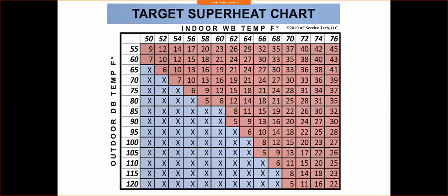It's going to tell you what your recommended superheat is based on the conditions. All right, so you've got this chart, and depending on what your conditions are, you're going to charge the system based on that. One cool app to have instead of having this chart, it's called Emerson's Check-in Charge. Really cool setup. Various amounts of refrigerant out there. You can do superheat, you can do subcooling. Real simple to use. I'll show you guys that at the end here what it looks like, but good stuff.